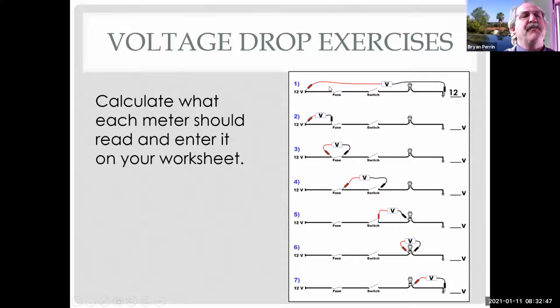If both of my meter leads are on the same side of the divide, they should be electrically the same. It would read 0. If they're on different sides of the divide, that means they're electrically different, so they have to read what that difference is. Another way of thinking about it is, take the red lead, which reads 0 volts, and the black lead, which reads 0 volts, then take red, subtract black, and here's the difference. So I've tried several different ways of explaining this.